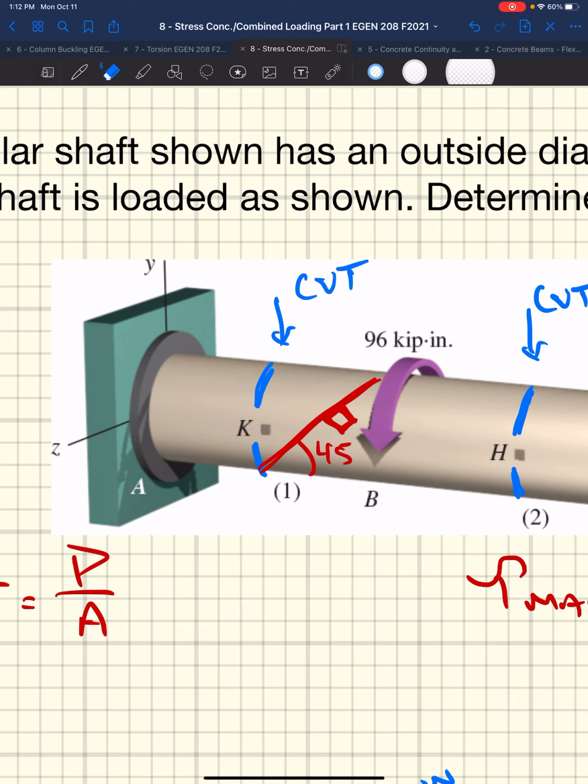And so what can happen is that the stresses we may look at that are perpendicular and parallel to the applied forces might be less than what might happen at a given orientation. So you can get maximum stresses at a, say, 54 degrees, and that's all based on the applied loads, okay?